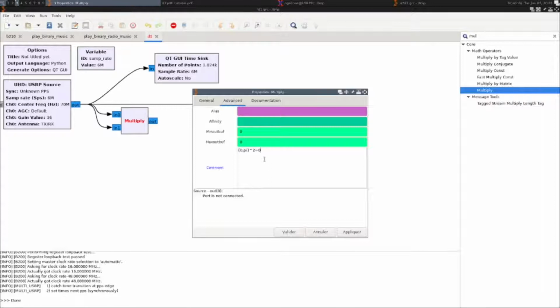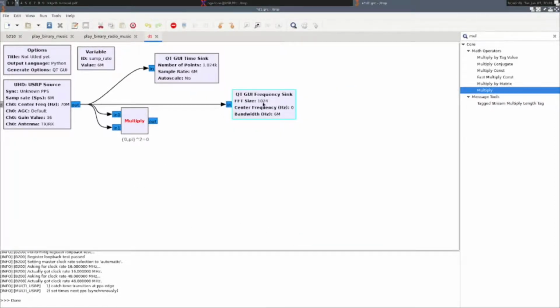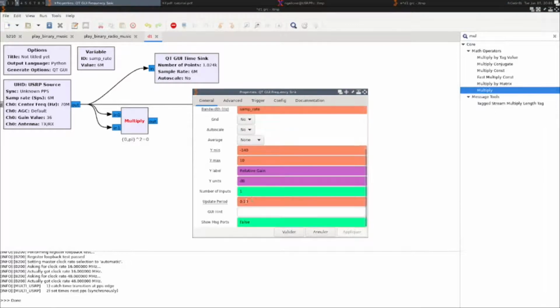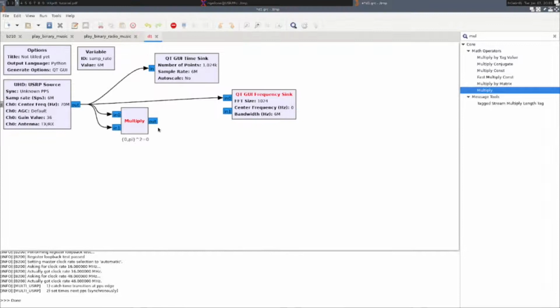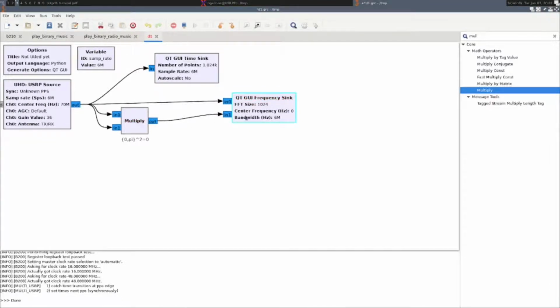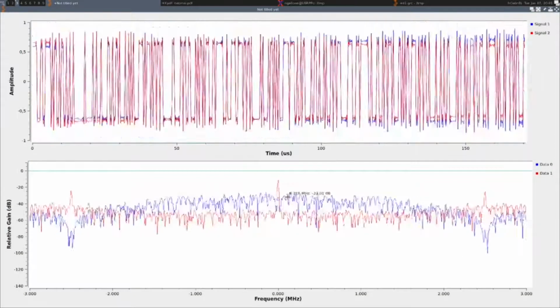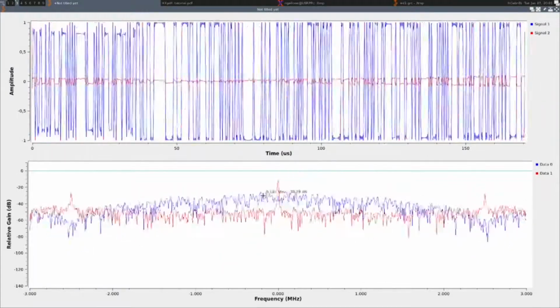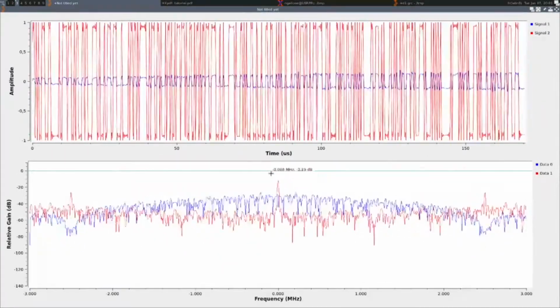So this means that we collapse all the energy in the carrier by doing this, and we should be able to see a clean carrier on the spectrum analyzer at twice the frequency offset, because by squaring we also double the argument of the delta f. So we have 2 times delta ft in this spectrum. And surely enough, here is the collapsed energy in the carrier.